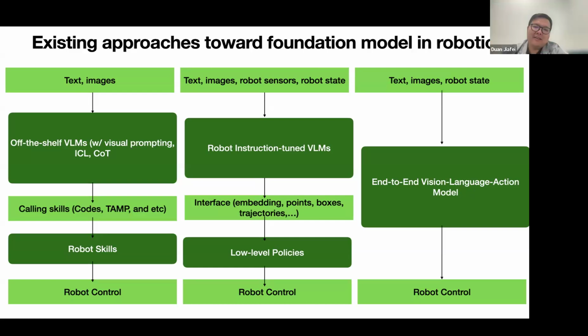Yeah. I do agree with what you're trying to say, which is that there's a lot of this problem, not just in terms of what you're saying here. Another way to look at this is, if you're talking about action-based models like VLAs, your VLAs must be able to do inference at a speed that is comparable to the action, correct? So there's a control frequency versus an inference frequency. If you're inferring too slowly compared to your action, then you might already miss the position to grasp, or miss predicting the next token.